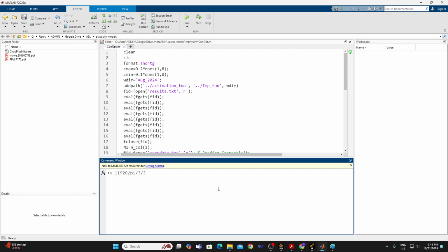So this is going to be our ultimate stress. So what are the 3's for? So you see it is pi r squared. So if 6 millimeter is the diameter, 3 millimeter is the radius. So if I divide 12 kilonewton by this much millimeter squared area, in megapascal 421 is going to be our ultimate stress.